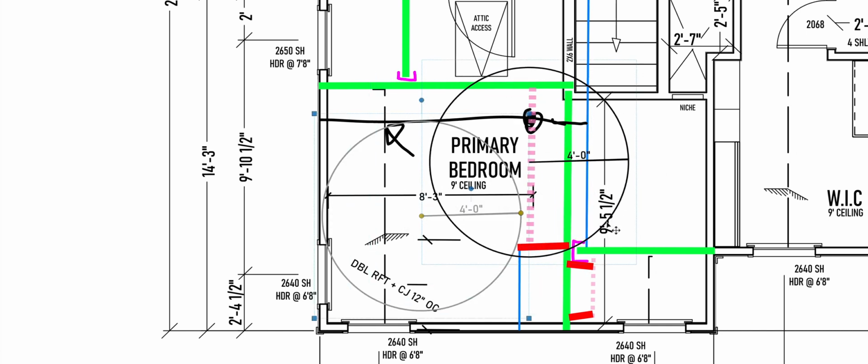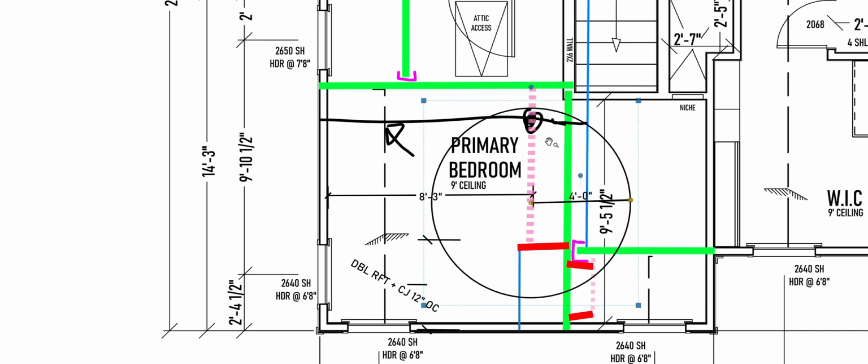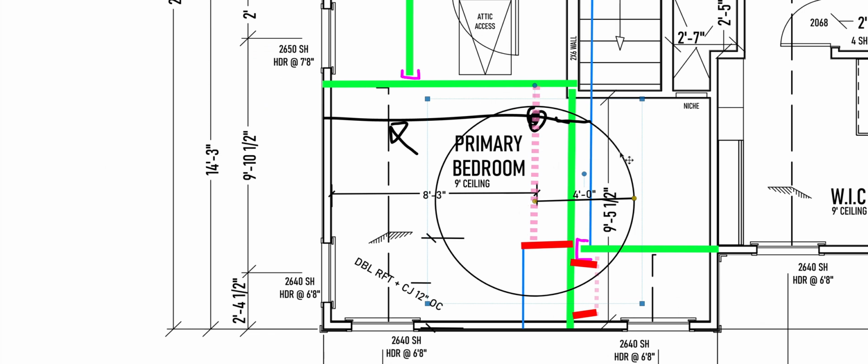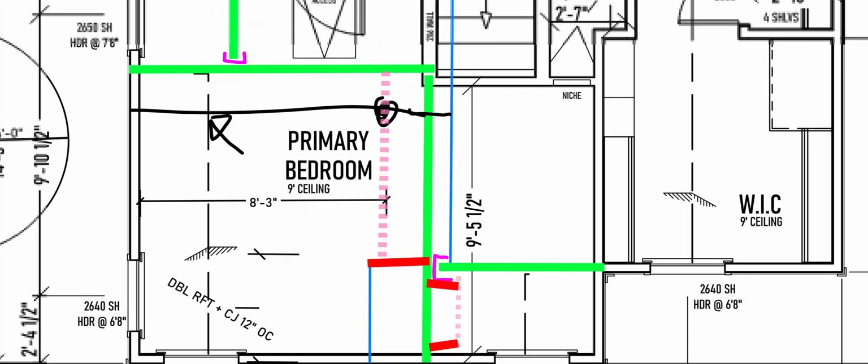So looks like I'm probably going to need 2 or 3 braces. It's going to depend exactly on where my purlin starts and ends when I actually frame it. But I need roughly 3 braces here. So I'm just going to move that out of the way. So I'm going to get my braces in here. One on the end for the purlin to the beam. One in the middle from the purlin to the beam. One on the other end of the purlin to the beam. Well, in this case, I could put it on the wall. It doesn't really make a difference because I'm using uniform loads later on anyway.